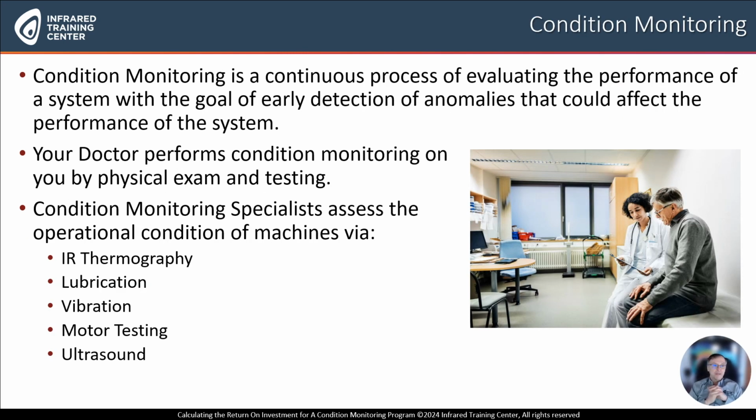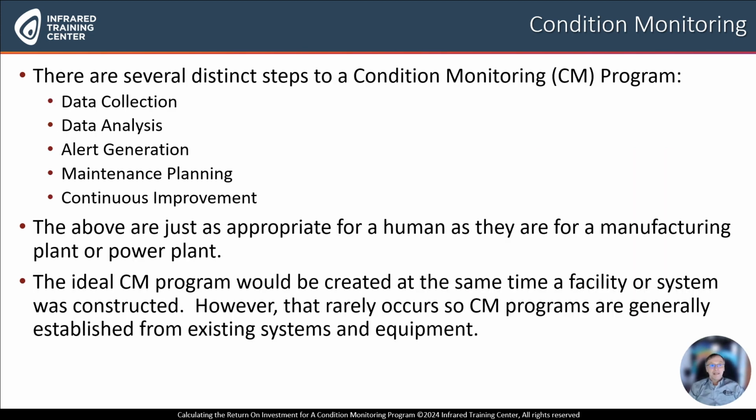What is condition monitoring? Well, it's a continuous process of evaluating the performance of a system with a goal of early detection of anomalies that could affect the performance of that system. Your doctor performs condition monitoring on you by physical examination and testing. Condition monitoring specialists assess the operational condition of machines via infrared thermography, lubrication, vibration, motor testing, ultrasound, and many other technologies. Now, there are several distinct steps to a condition monitoring program.